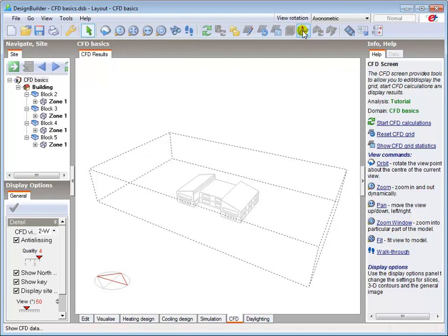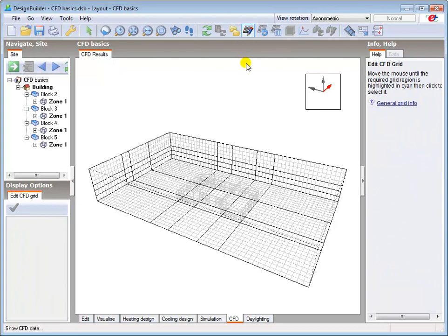When a CFD project is created, a grid is automatically generated for the required model domain by identifying all contained model object vertices and then generating key coordinates from these vertices along the major grid axes. These key coordinates, extended from the X, Y and Z axes across the width, depth and height of the domain respectively, are known as grid lines. Grid lines are grouped together into grid regions, and these regions are initially spaced employing the user-defined grid spacing in order to complete the grid generation.